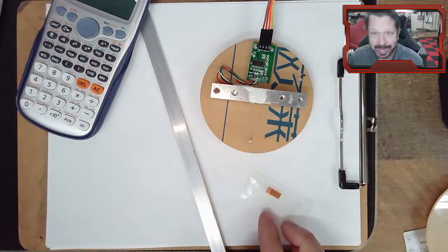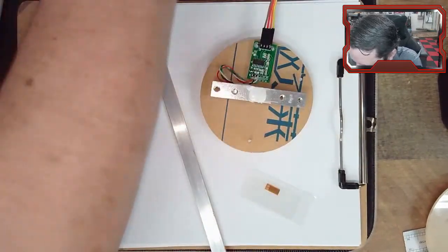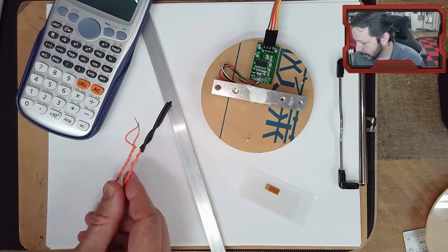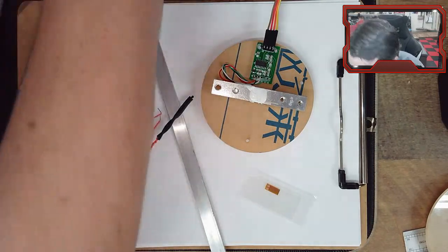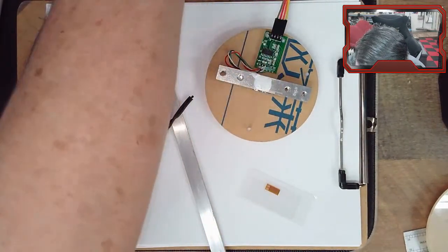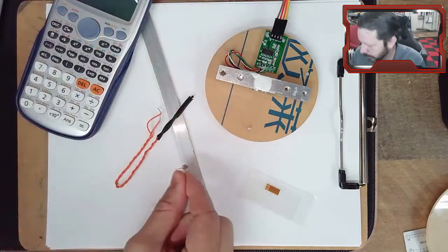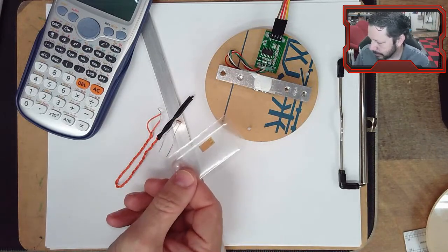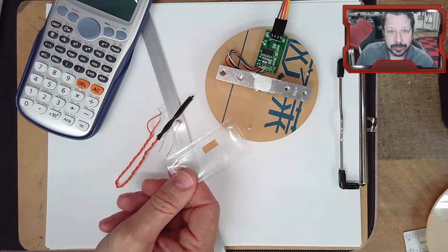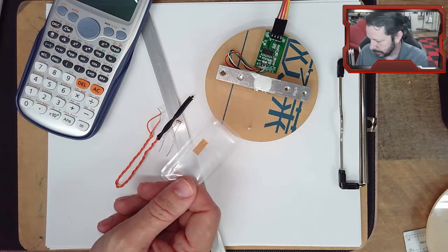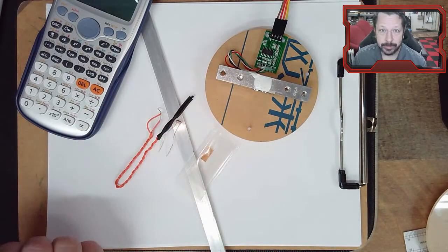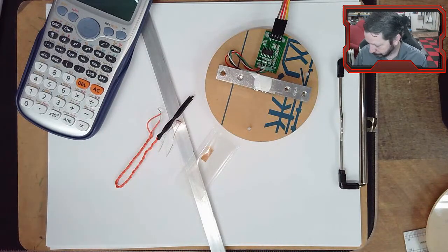It's very tiny. We had the thermistor, which changed its resistance based on temperature, somewhere. We also had a photoresistor. I think I've lost that temporarily. No, wait, here it is. We had a photoresistor. It changed its resistance with light level. This guy changes its resistance with strain. So as strain increases or decreases, then its resistance will change. And so you can kind of see a theme here of changing resistance that we need to measure. And so this HX711 helps with that.